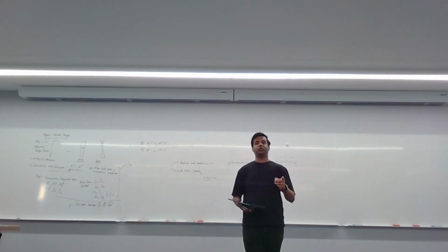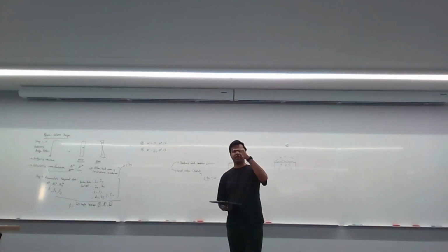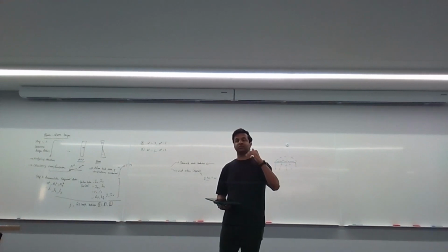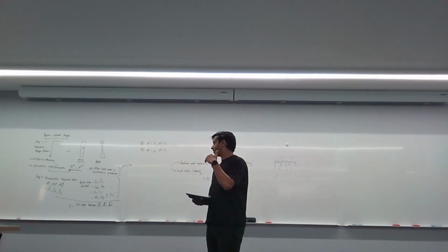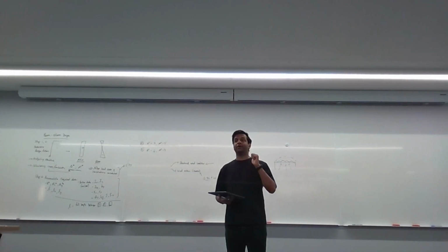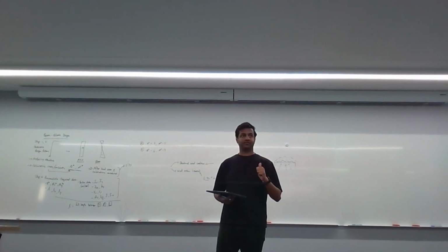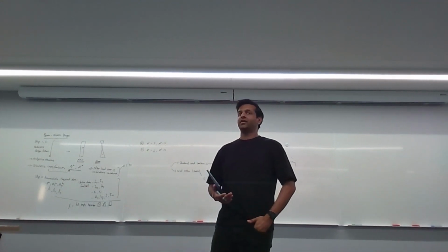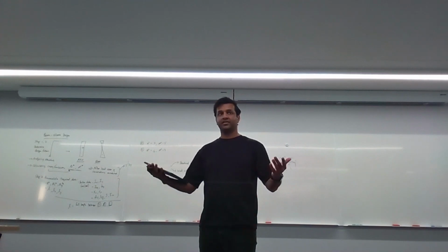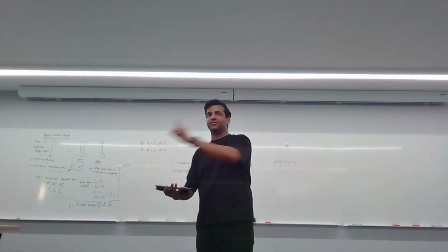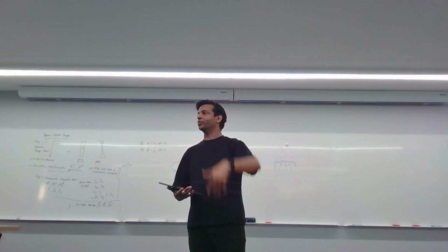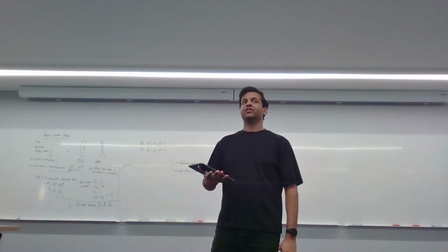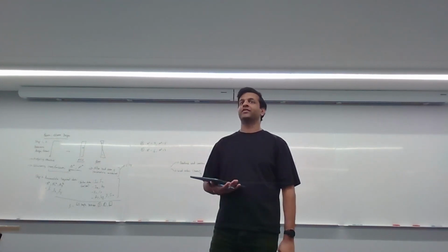Okay. So have a look through the notes, have a look through the code AS4100. There are point forms that are given to you of what constitutes a full restraint, what constitutes partial, and what is lateral restraint only. The important thing you've got to remember is what is the critical flange. So as a recap, if you have a beam that's supported on both sides, so you've got two pin supports on each side, and there's a downward load, can anyone tell me which flange is the critical flange? The compression flange on the top or the tension flange on the bottom?